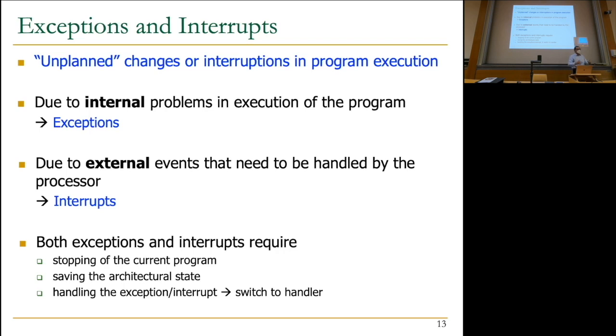Here, you basically go to a handler that executes code to get the data out of the keyboard and puts it into an appropriate place that it needs to go to so that the system actually does something with it, right? Okay, and in the end, if possible and makes sense, you need to return back to the program execution because you interrupted, stopped the program, you handle the exception or interrupt, and then you put the program back on the processor and continue executing from where you interrupted the program.